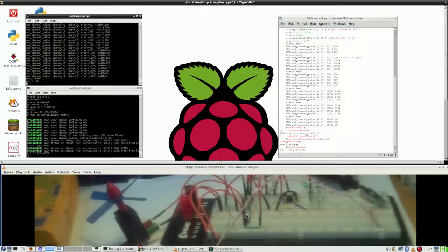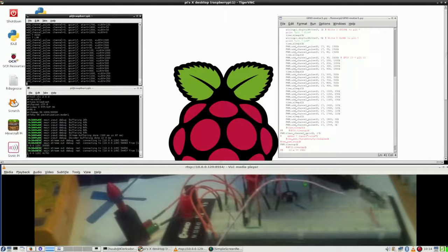And now there's a problem, because there's a voltage, which I measured, 4.7 volts over this transistor, and that should clearly illuminate this LED, and this LED doesn't do anything. So I have to measure the voltage on this wire, which is 4.13 volts.